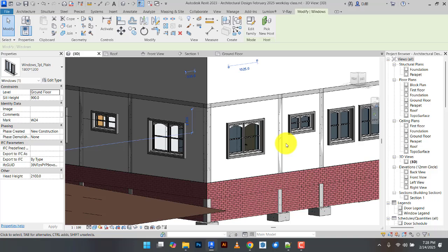If they give you a PDF of the drawing, that way you know the dimensions are correct. You can bring the PDF here and draw your walls on it, then it will form for you. But if you bring the PDF, there's a way you do it. You don't just bring it and draw on it. When you bring the PDF, you have to scale it, so you have the scale correct. So when you draw, you get the exact size. You can bring the PDF or the image, but if it's not scaled, you get different room dimensions.